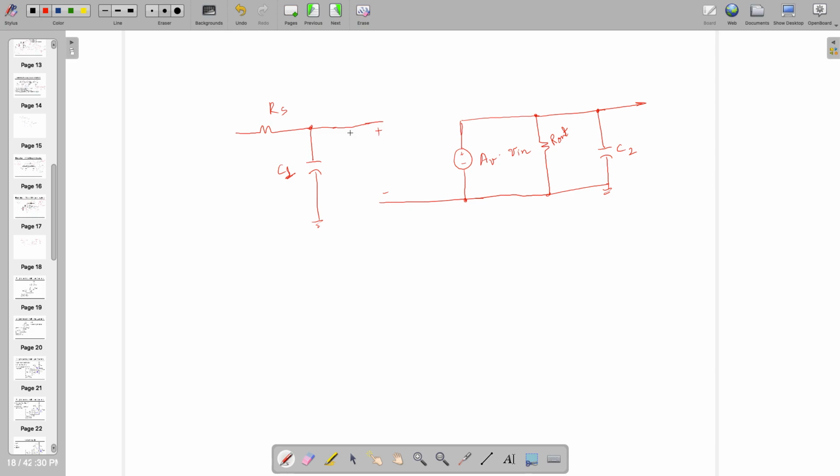So in ideal condition input impedance is infinite, and looking at the resistance in shunt with capacitor C2, or effective impedance looking into this circuit or at this node while keeping all other effective voltage sources to 0. So this is also not going to be considered, right?